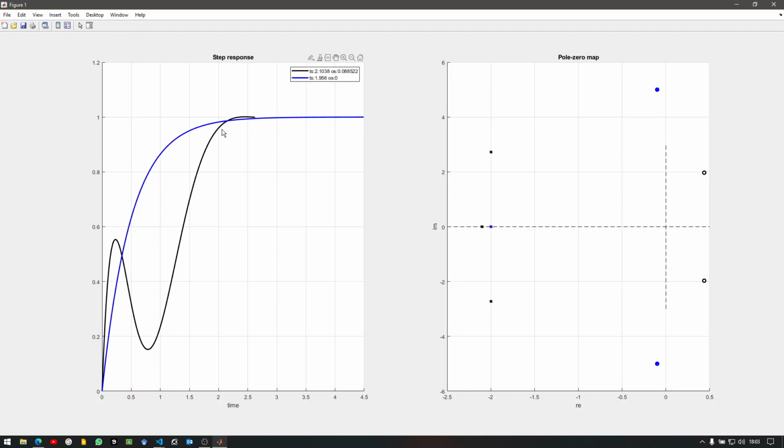This behavior is not that optimal. So what is the reason behind that? Well, of course I have cancelled the poles with the 2 zeros that were available here. At that point I'm only left with just one pole that is on the real axis, and as I've done it earlier, I just have picked the value of 2 because I was looking at a pure integrator.